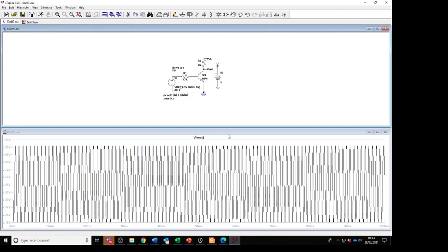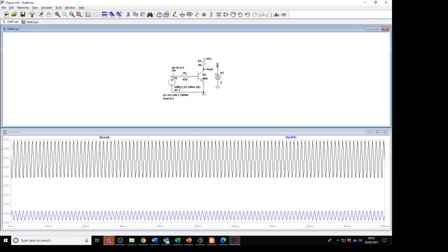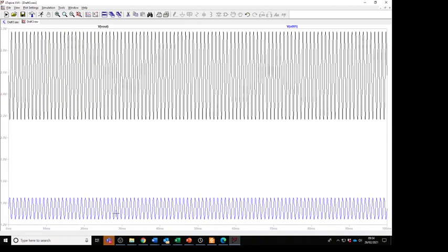Okay, and so now we can look at V out, because that's what it's defaulted to, and we're getting a sine wave out. We can start to look at the numbers to see whether or not it's what we expect it to be. What we can also do is click on here to see what the input was. And you can now see, if I make that big, that we've got a small input centered around 1.36 volts, and we've got a much bigger output centered around roughly 2.5-ish, which is what we sort of expected.